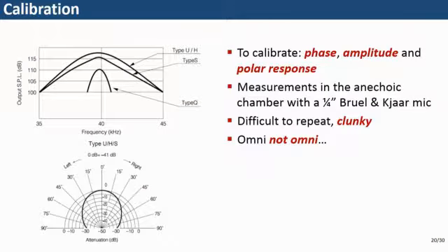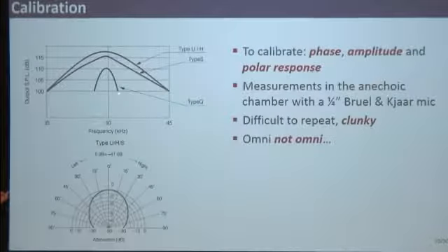Calibration. Calibration is important. Of course it's important. We want to have perfectly calibrated things. For example, here we have the frequency response of our transducers, actually of some other transducers, but all of them are roughly the same. So you see that at 40 kilohertz, they're the most efficient, okay? And as you move away from 40 kilohertz, they are less and less efficient. So we want to equalize this.